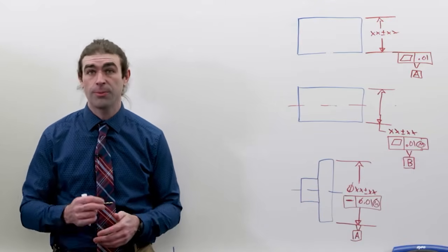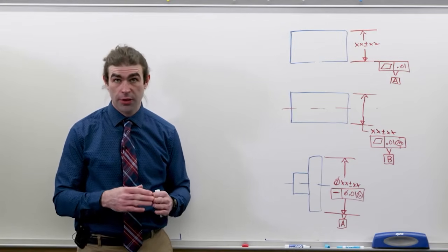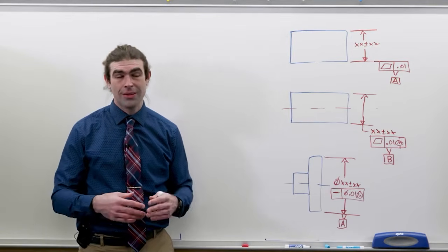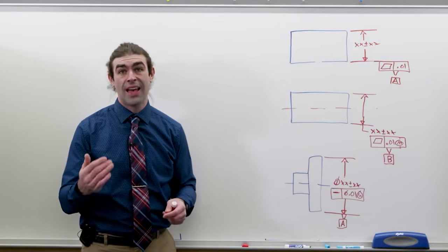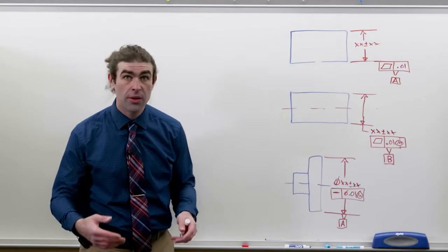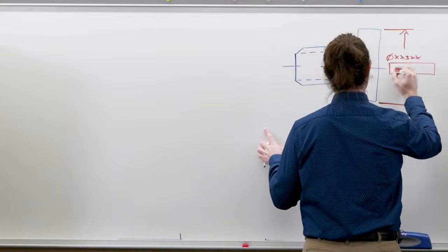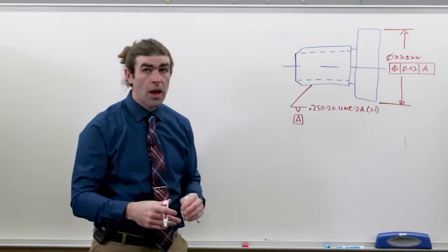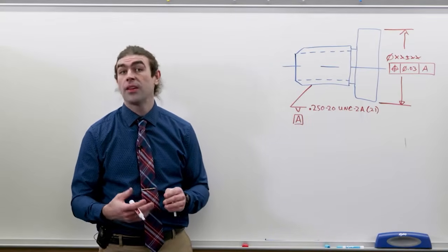But rules change. Now, I want to take a look at a couple other types of datums. The planes and cylinders are the most common. Most parts you can get away with either a surface plane, center plane, or the axis of an internal or external cylinder for a lot of your datums. But it's also somewhat common to see threads called out as datum features.